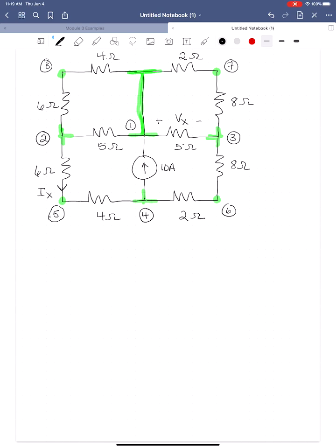Okay, I'm going to highlight in a different color just to make a point here that this is all one node here. It can be real tempting to label a node at this point, a node at this point, and a node down here, but they're all one node. Think about the wires like silly putty. We've stretched the node out to make this nice boxy circuit.